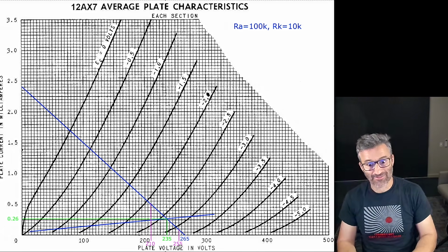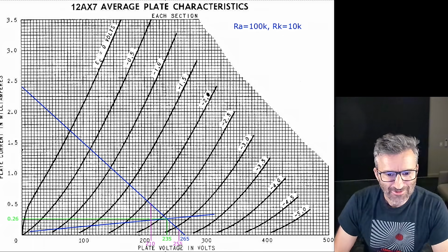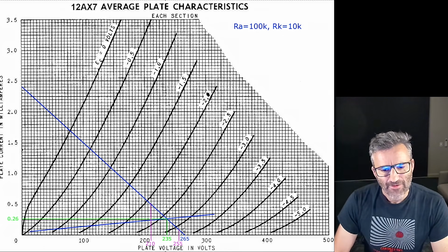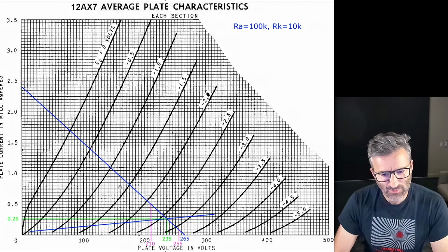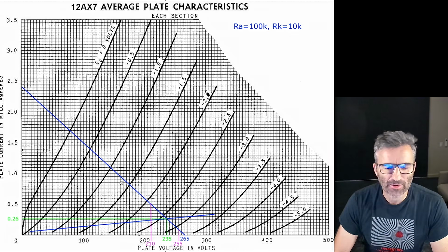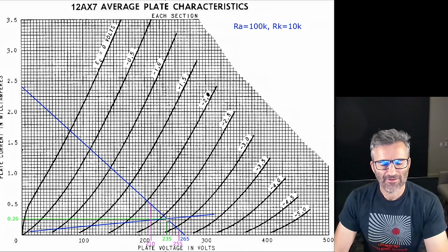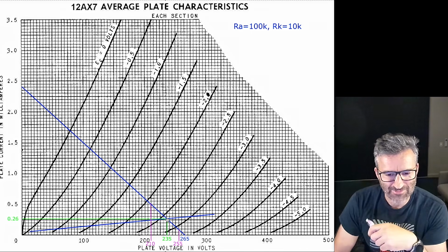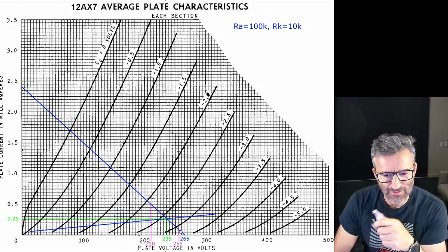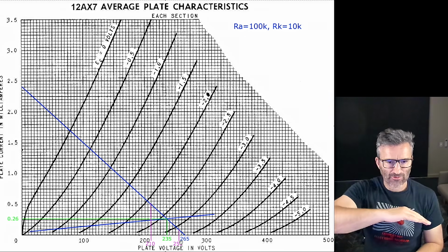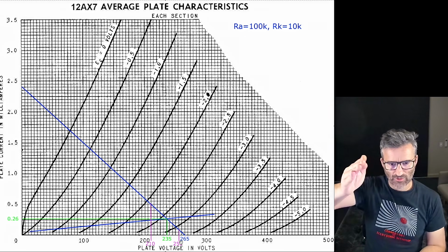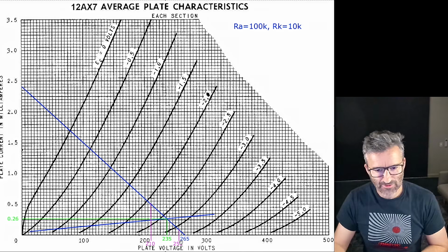So that's the gain, right? The gain is 45. So we're definitely getting gain here. It's not as much as you get if your operating point's down this end here, and I'll show you why. But with the 10K, as I just said, it takes next to nothing to push this side of the waveform into cutoff. And when you go into cutoff, what you get is a square wave. We'll show this on the oscilloscope.